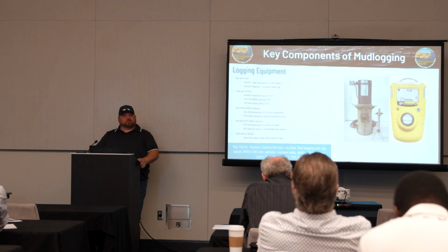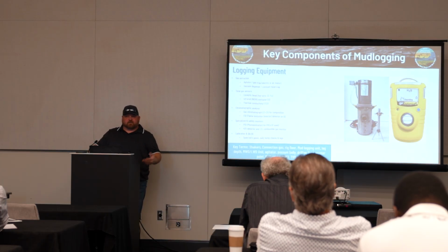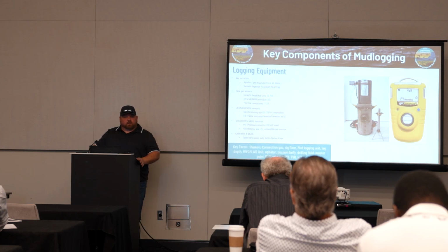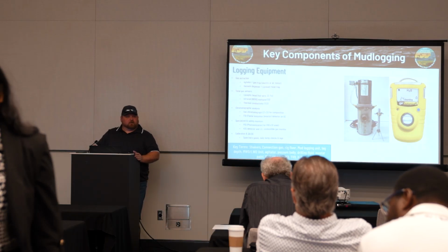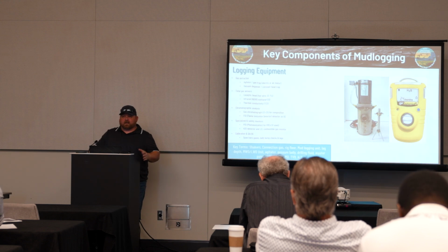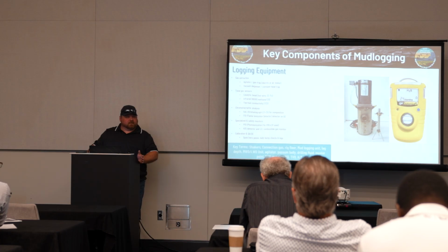Most generally, you'll have dilution of other gases, nitrogen, carbon dioxide, stuff like that, whereas when we're calibrating them, we're testing with pure gas. So 10,000 units would be your high. We usually calibrate it to 9,900 because you don't really ever want to max out a sensor.